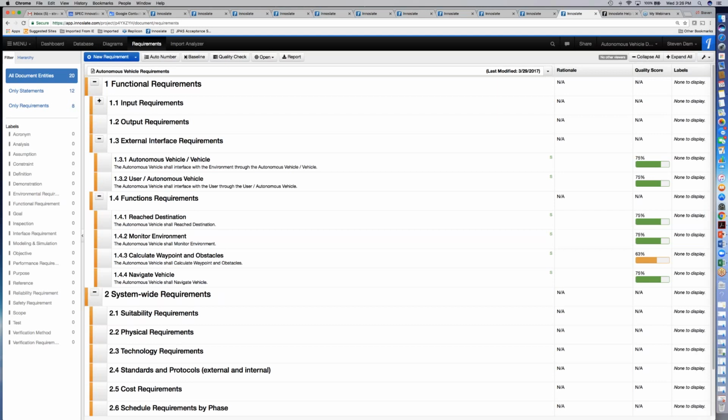All right, our last question is, I have a rambling wish list narrative from a customer and a PDF that I have imported. I have started decomposing it into a Word file of requirements that I also want to import. The PDF import needs to be edited because it did not import perfectly. Then I need to link all my Word requirement statements to the PDF to give traceability back to what the customer wished. I also need to output a traceability matrix. How do the PDF editing, traceability, and matrix output work?